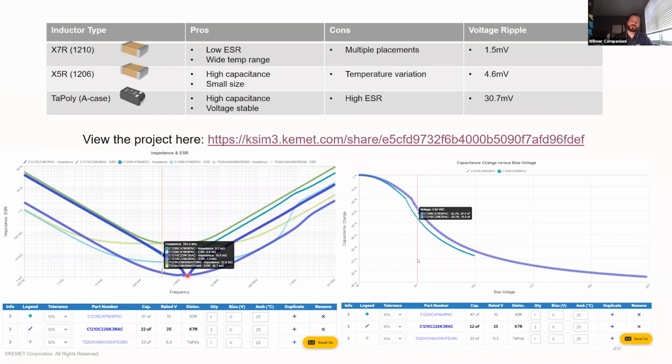Yeah, so ultimately, the more heatsink you have, the more temperature you can drive essentially with these capacitors. So you know, really big, thick copper traces attached to these components obviously will sink a lot of heat out of that device. So that is a factor that must be considered.